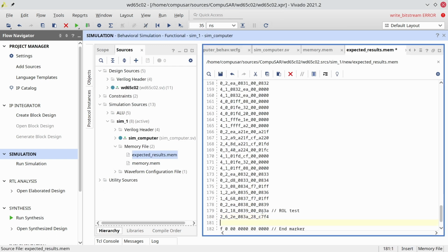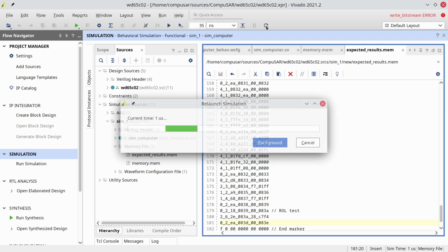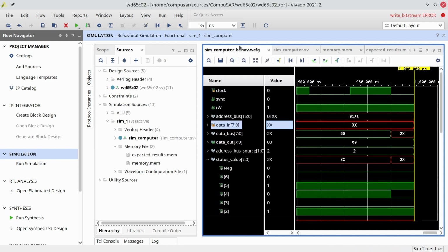And we finish it off with another no operation, which is an implied operand, 2 cycles. The opcode is EA. It is read from 083D. We're not interested in what it does. And the last access will be to 083E. So that's our test plan. That's what we expect the program to do. Unsurprisingly, that's not what it will do, simply because we haven't implemented the opcode yet.